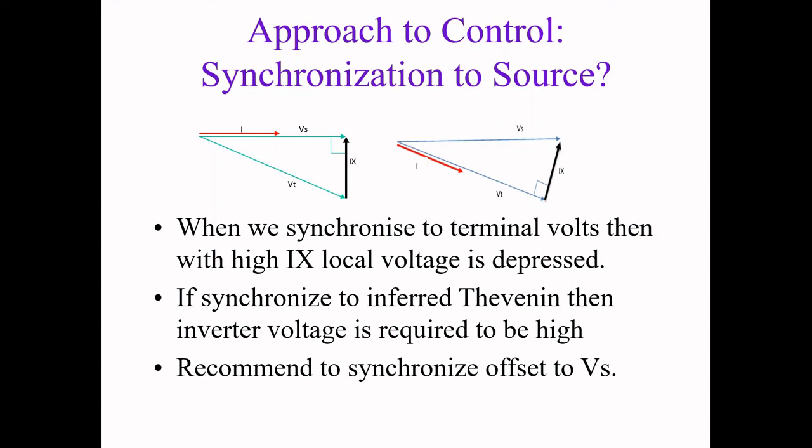Fault levels are a different thing, right? So there's the small signal weakness, and then there is the large disturbance weakness, the large disturbance weak grids. And it's the large disturbance weak grid model that's being used mentally as a way of describing what's weak, and not necessarily looking at the support that is potentially available through inverters for small signal weakness. So small signal weakness can be overcome by having voltage support mechanisms.